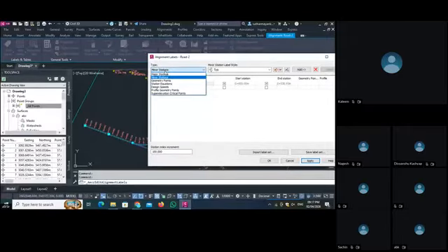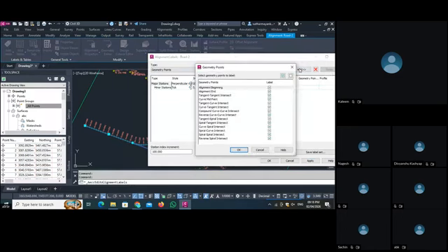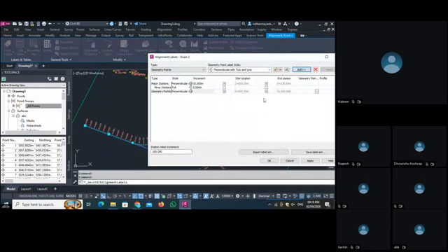If you want to add geometry points, you can add your geometry points also. If you select the add button, the pop-up is here. I don't want to see all those things because if I insert all of them, our alignment will be messy, and if we send a messy alignment to anyone, it will not create a good impression. So I don't want this. The important points only I'll show here. The rest of the things I uncheck, and then I say okay. So your geometry point is also added.